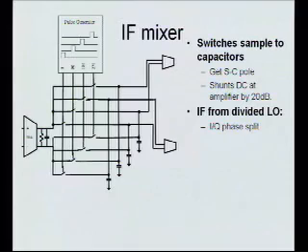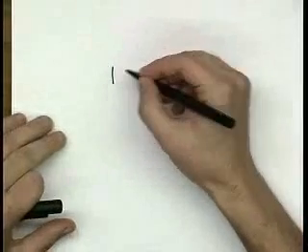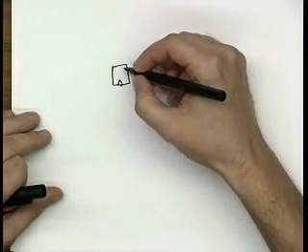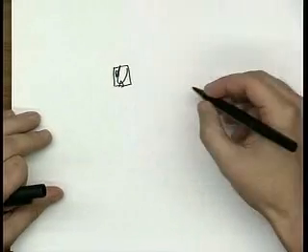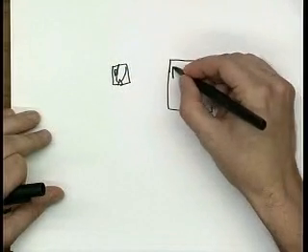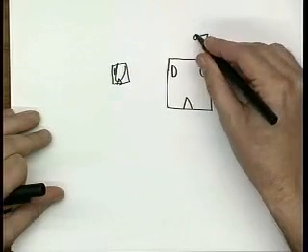Okay. Can we go to the paper? So the basic idea is a divide by 2 would look like, that's right. You might do it like this. You have a D flip-flop. This is too small. I did learn from my feedback forms. So this is a T flip-flop overall.